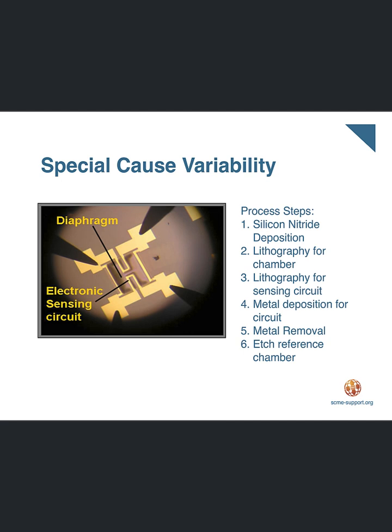Consistency is key, and any change in variables that is unacceptable can lead to defects either immediately or in a subsequent process step. This is where SPC comes into play. SPC helps us determine statistically what the inherent variation of the process is and identify a process that is, as one would say in SPC, going out of control due to a special cause or an unassignable cause. SPC allows us to identify problems immediately and correct them before they affect other parts of the process.